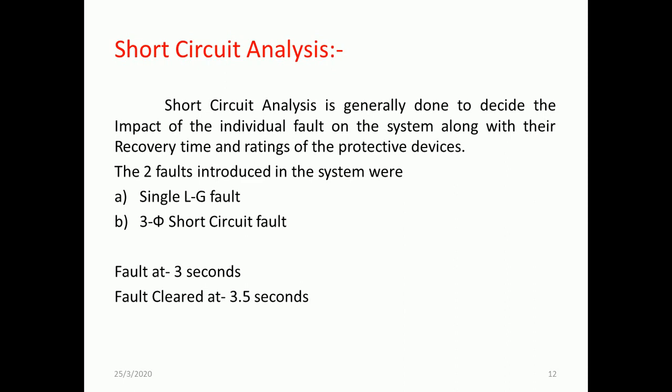One more analysis which you can perform in the software is the short circuit analysis. Short circuit analysis is very important when you decide the rating of the protective devices. You want to make your system ready for an abnormal condition and recover from it. So short circuit analysis is generally done to decide the impact of an individual fault on the system, with the recovery time and ratings of the protective devices to be implemented.